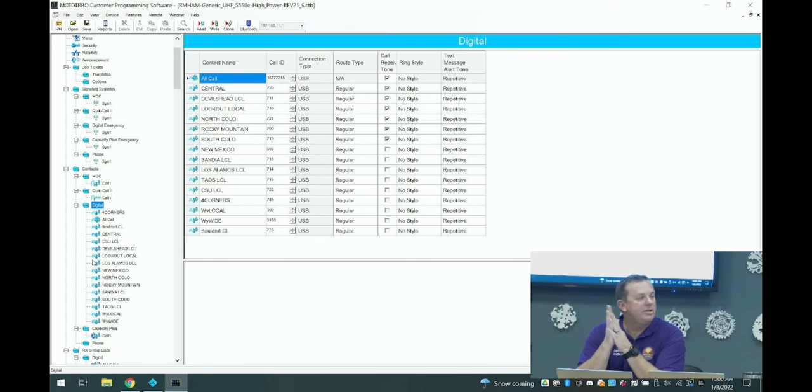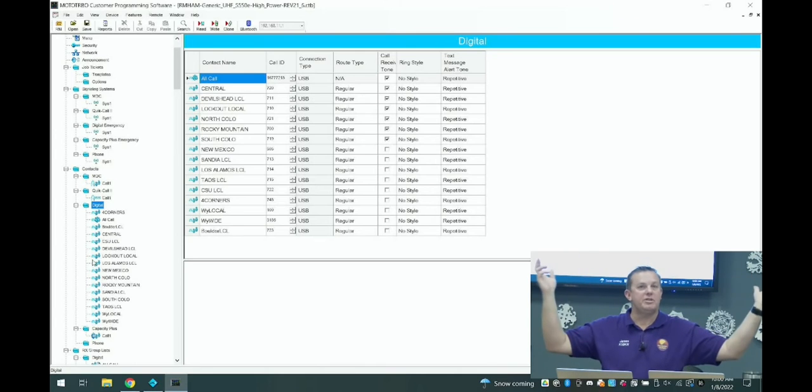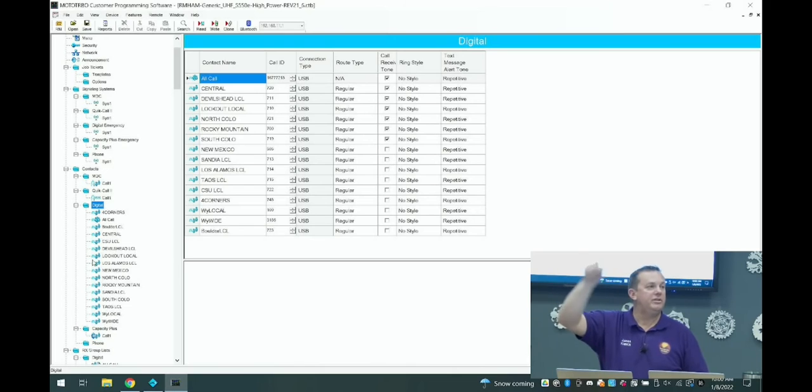Why do we have those? Well, in the individual contacts, remember in a commercial system, maybe we want the public works guy to talk to the other public works guy and they don't want to tie up the whole system and have everybody hear that. These radios are capable of making that call, one ID to another. We discourage that use because it ties up the entire system. Since we don't have a trunk system with many repeaters for those folks to share, it ties up that whole talk group, that whole part of our system.